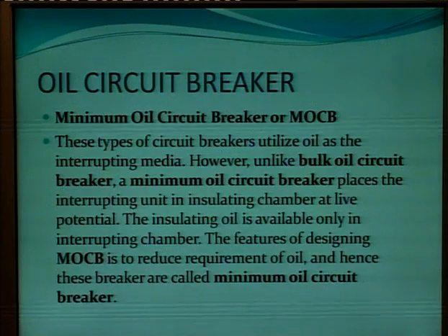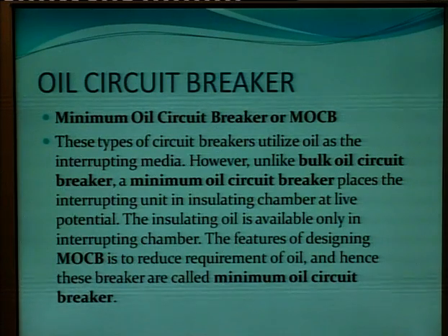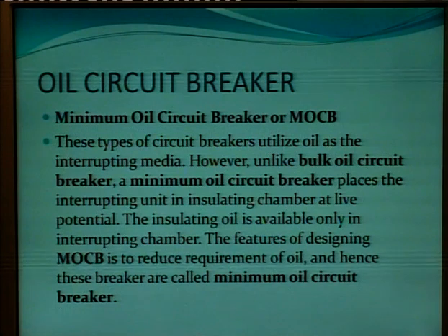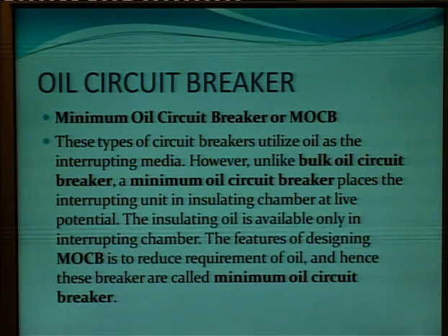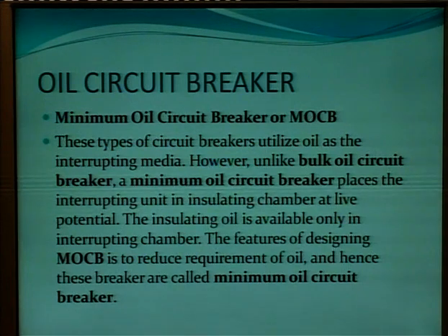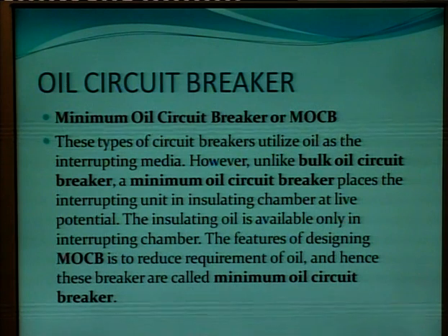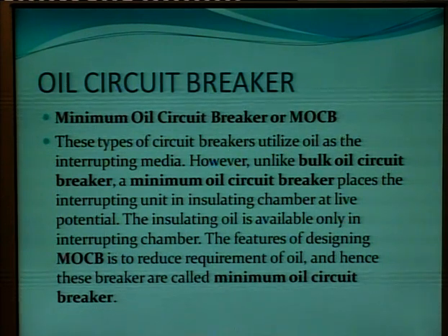Insulating chamber at live potential. The insulating oil is available only in the interrupting chamber. The feature of designing the minimum oil circuit breaker is to reduce the requirement of the oil, and hence these breakers are called minimum oil circuit breakers.